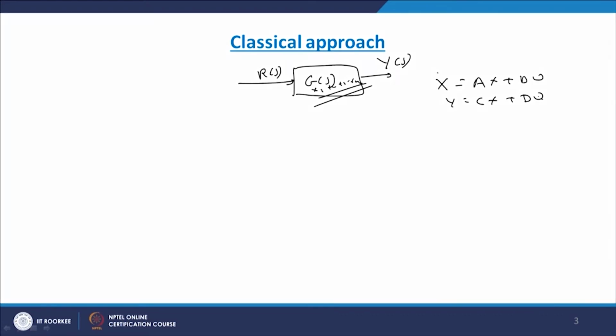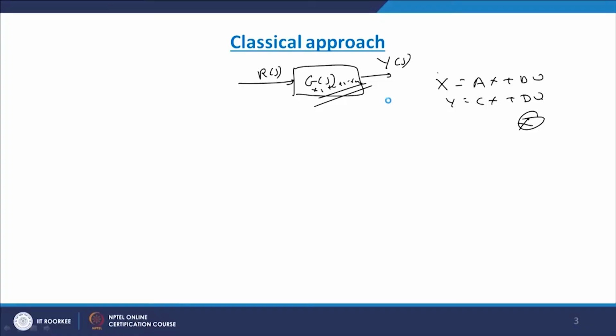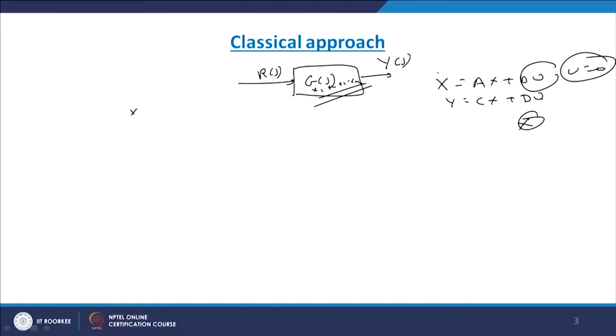When we are concerned with the state equation, we are only concerned with x. Here we are assuming the unforced system, that is, the case when u equals 0. So when u equals 0, we have the state model x dot equals Ax. So what is the state equation? We want to know x of t, where x dot of t equals Ax of t.